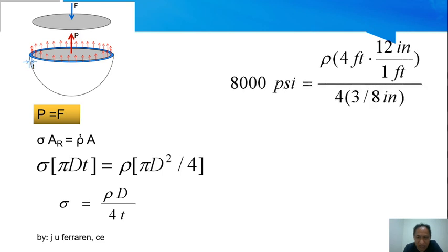And after knowing this formula, I can proceed with the substitution of the given. The allowable stress is given as 8,000 psi. We are required to give the internal pressure. So, my internal pressure unit will depend on the unit of the stress. The diameter and the thickness must bear the same unit to eliminate the unit for the ratio.